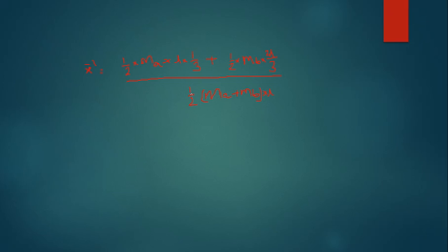You can take out the common value half, L by 2 on all sides gets cancelled, and here L over here and here gets cancelled. Here also actually L should be there, area half into MB into L. So we are left with a common value L by 3.